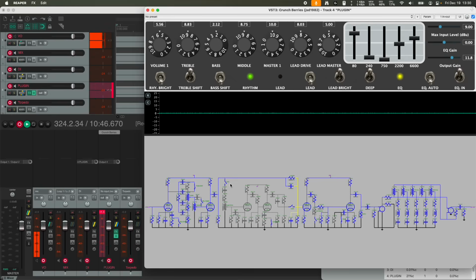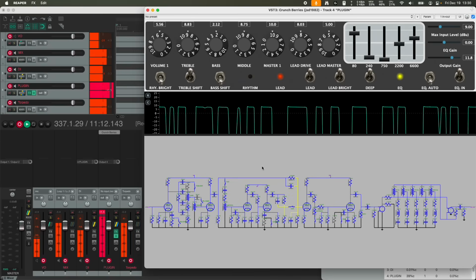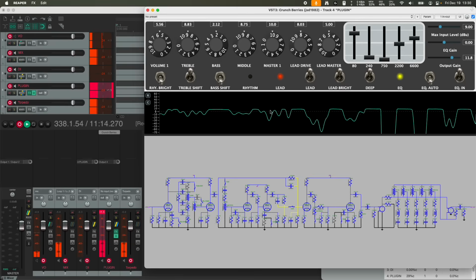Right. The 2C Plus is famous for doing this additive gain stage. So the lead mode, all the overdrive, is right here in these 2 tube stages and these supporting components. So this massively amplifies the signal to the point of clipping, obviously beyond clipping, in these 2 triode stages. So if we enable the lead mode, you'll see most of the distortion coming from this section. And yeah, there you go. It's a big square wave.